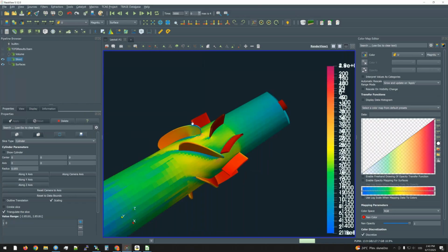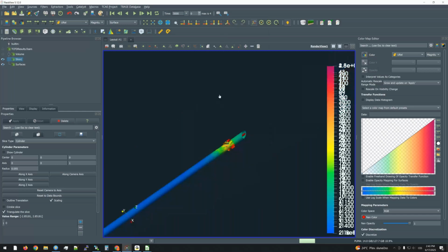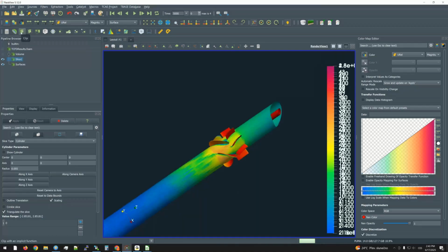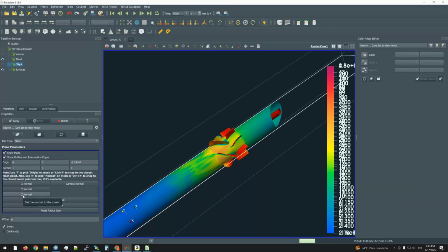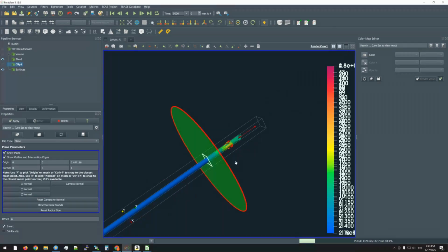and now I can, for example, visualize the velocity contour. And for example, what I would like to see is the relative velocity on the rotor side. And now, for example, now I would like to apply the surface LIC filter, which will nicely visualize the surfaces. But because my domain is pretty long, I would like to cut it. So on this slice, I can apply the clip. I would like to clip it by the plane which is perpendicular to the Z direction, and I will move somewhere here.